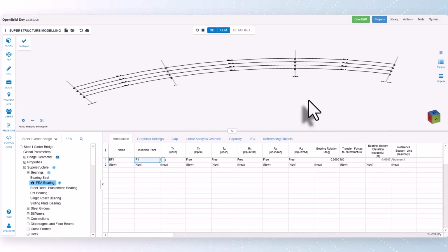Two fundamental approaches are used in structural analysis to define bearing behavior. Rigid constraints assume that the bearing either completely prevents movement or is completely free in the relevant direction. In the fixed state, force and moment transfer occurs, while in the free state, force transfer in that direction is zero. Spring stiffness values, however, recognize that no connection in the real world is perfectly fixed or free, and define an intermediate rigidity behavior. Here, the bearing provides resistance with a certain flexibility proportional to the applied force or moment.